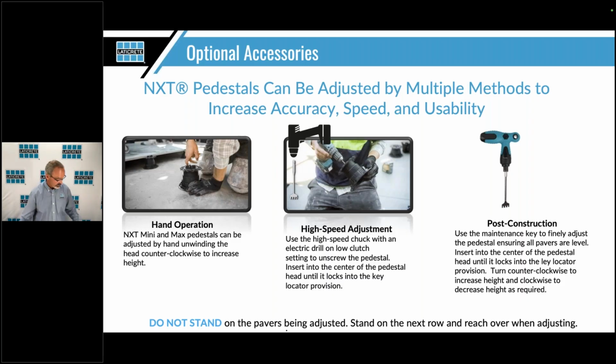Now after construction, you can have one of these. The same tool fits right inside here, and basically that will fit down the same distance as your spacer gap. So if you need to, you can go back in and tighten and loosen these pedestals once they're actually installed. So that's kind of a post-construction thing. So by hand, if you're doing a lot of adjustments, using the drill, the screw gun, and the post-construction tool will really help you along.